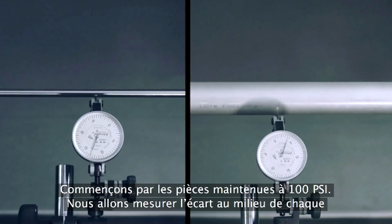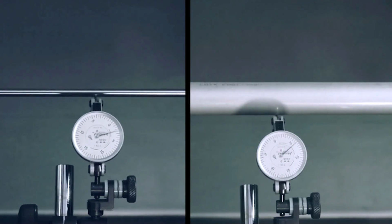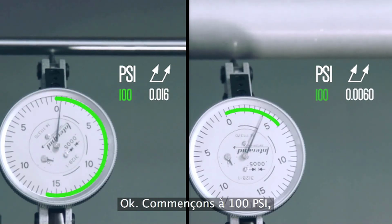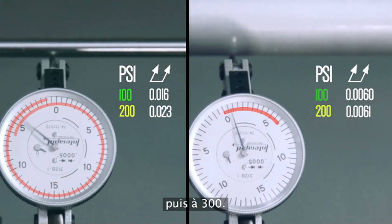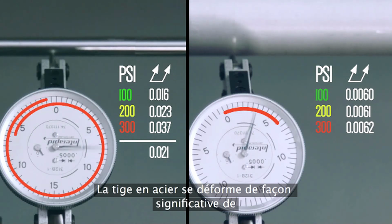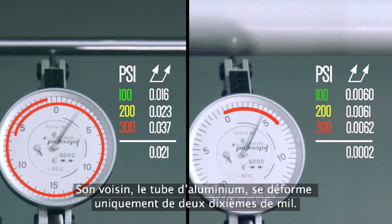Starting with the parts held at 100 psi, we'll measure runout at the middle of each part as we make 100 psi tailstock pressure increases. Okay, starting at 100 psi, increasing to 200, and then 300, the steel rod deforms significantly by an additional 21 thou. Its neighbor, the aluminum tube, deforms by only 2/10.